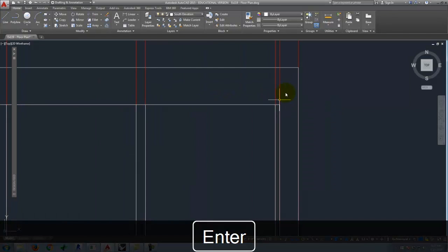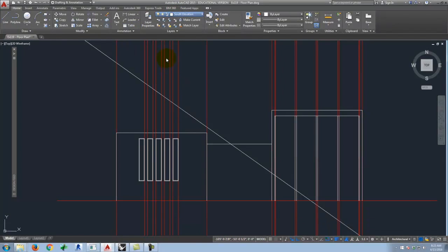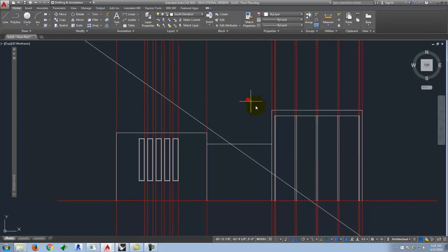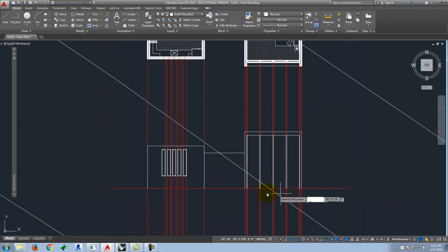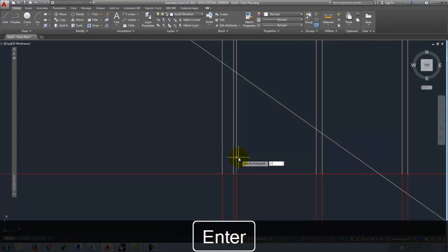There. So if I were to look at this without the guides, sometimes it's easier to see it without the guides. Let me temporarily turn those off. You can see that I'm starting to establish, okay, there's one piece of my building. I haven't drawn anything here. And this end, okay, I have the windows, but I need to divide those up into some panes of glass so they look a little bit more realistic. So let me turn back on those guides again. And let's say that the bottom section here, I don't know, we'll go up maybe 2 feet.